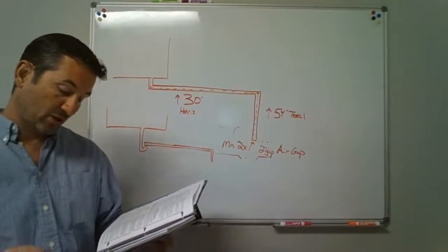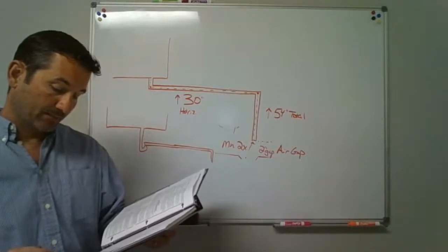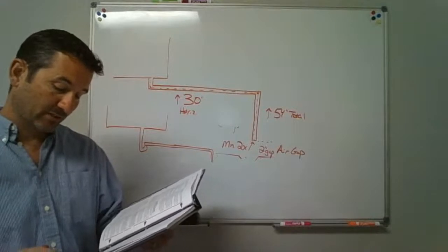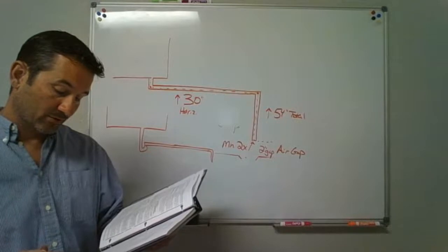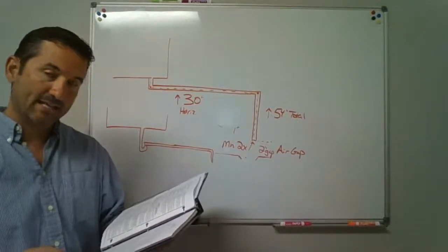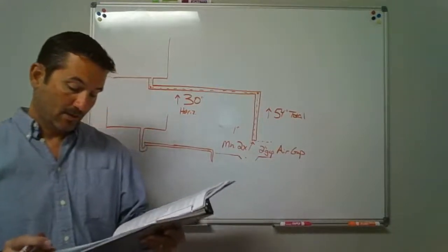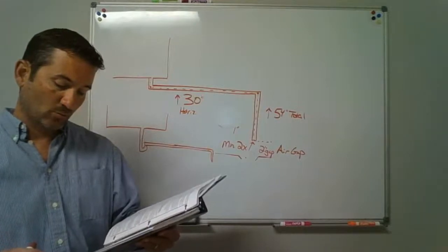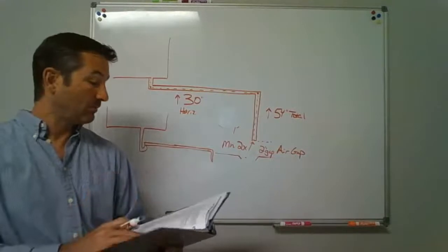Waste receptors should not be installed in plenums, crawl spaces, attics, spaces above ceilings and below floors. Ready access shall be provided to waste receptors. Ready access, not just access, but ready access. Exception, where hub drains are installed in a crawl space for condensate waste is allowable.